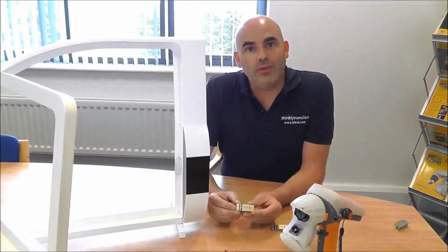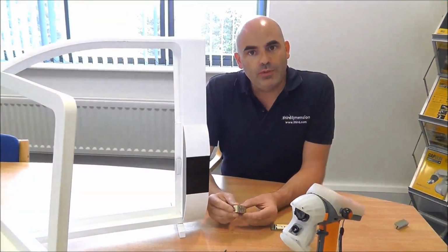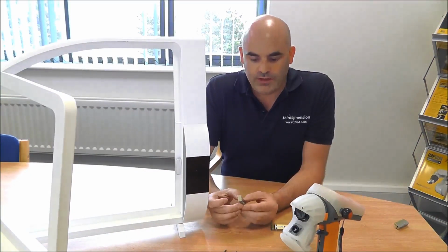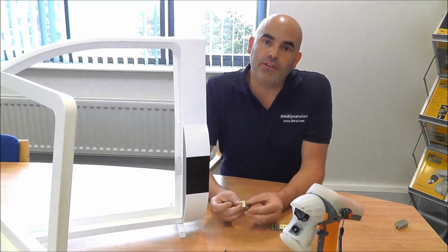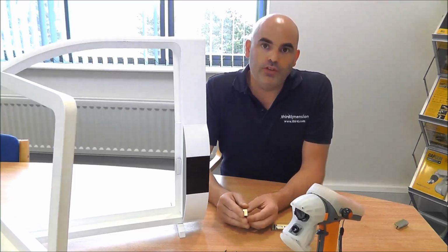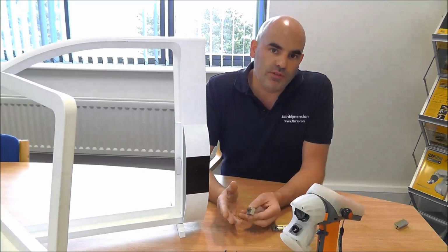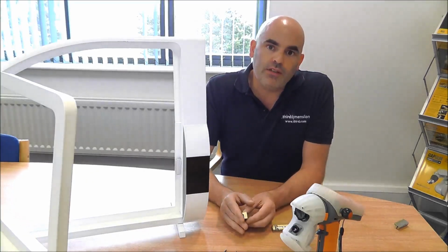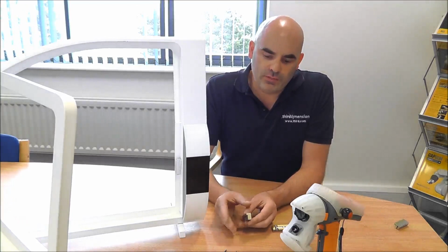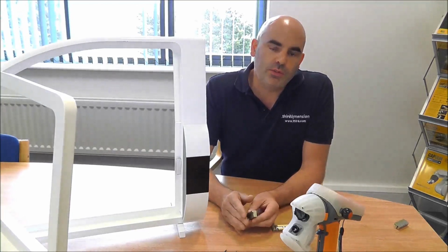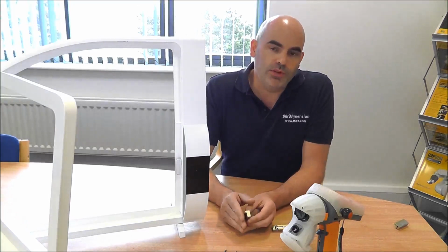Now we're going to take a look at how we use the seal blocks. First of all, we need to install them into position on the door. Once we've done that, we pull the plunger to its maximum height. Once it's installed like that, we simply close the door and that will push the plunger to the height of the seal gap. And then we will use the GapGun with its special seal gap standoff to collect the measurement data from the blocks.